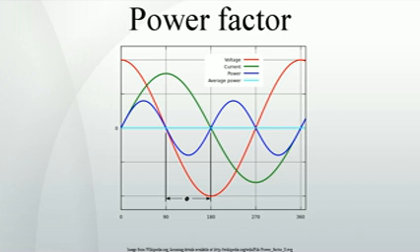When power factor is equal to 0, the energy flow is entirely reactive, and stored energy in the load returns to the source on each cycle. When the power factor is 1, all the energy supplied by the source is consumed by the load. Power factors are usually stated as leading or lagging to show the sign of the phase angle. Capacitive loads are leading, current leads voltage, and inductive loads are lagging, current lags voltage.